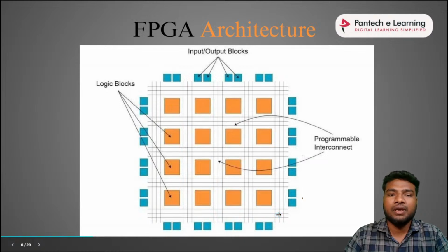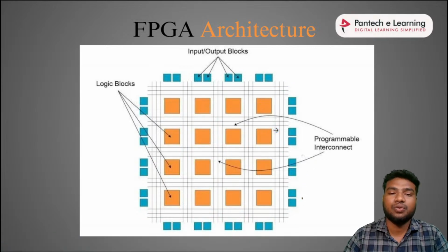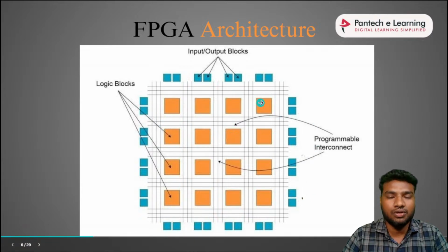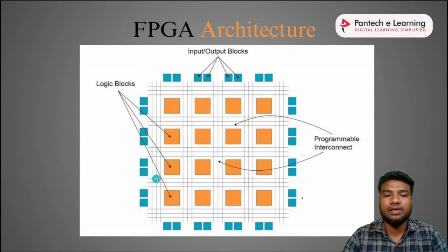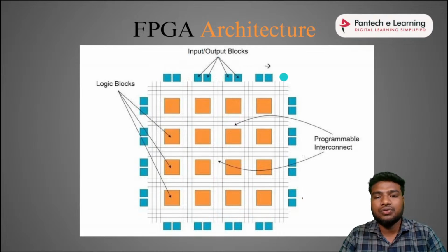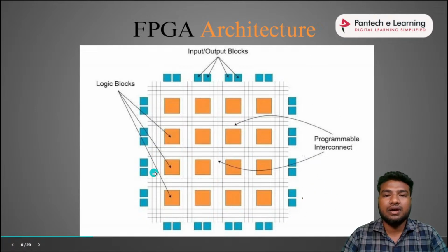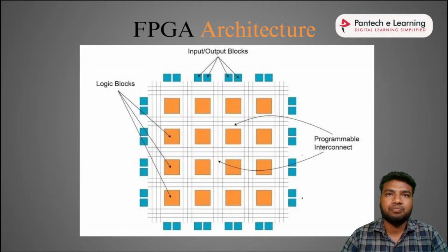This means in an FPGA board we can make the PCB in an easy way. If you have the inputs here and outputs there, it is very hard to make a PCB design. This is an IC, and from this IC we have to make an FPGA board. If you follow this architecture, we can easily make an FPGA PCB. Only for that reason they use this architecture, so all sides have pins. Each side is like a bank. This side is the first bank, then the second bank, third bank, and fourth bank. These banks also let us identify the pins in the FPGA. The main thing is that for making the PCB and the circuit easy, we use all sides as IO banks, IO pins.